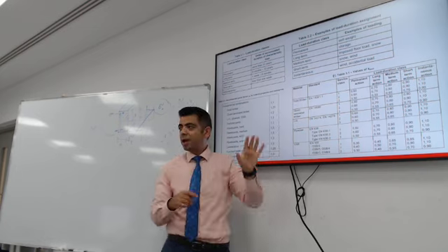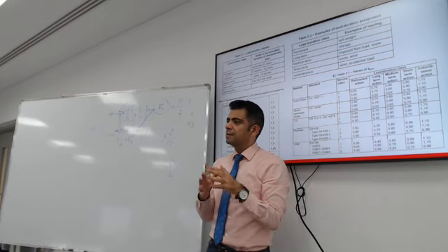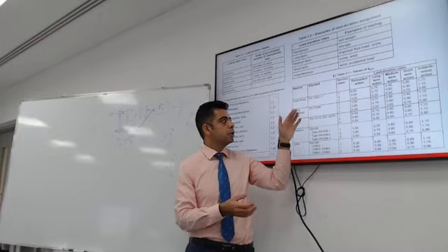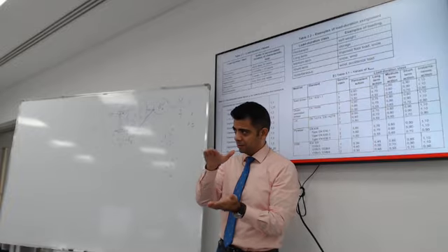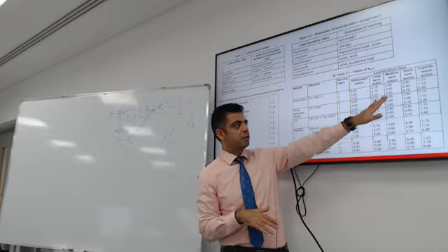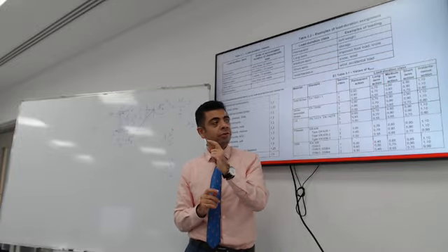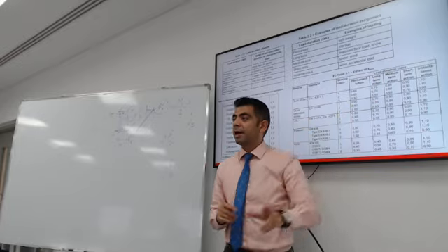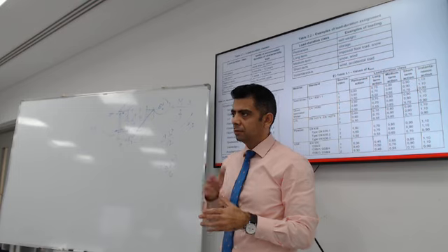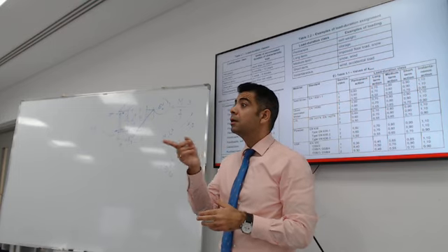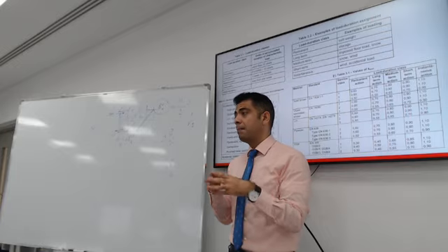For each type of wood, it's not types of wood, it's like a product, wood products. If it's an engineered wood like Glulam, you take into account that this is not one natural piece of wood. This is pieces glued together. So obviously the factors might differ. One last thing to take into account. The load duration class. Can you guess what the load duration class is? Lifetime of applying the load? Yes, the duration of the load on the structural element matters.